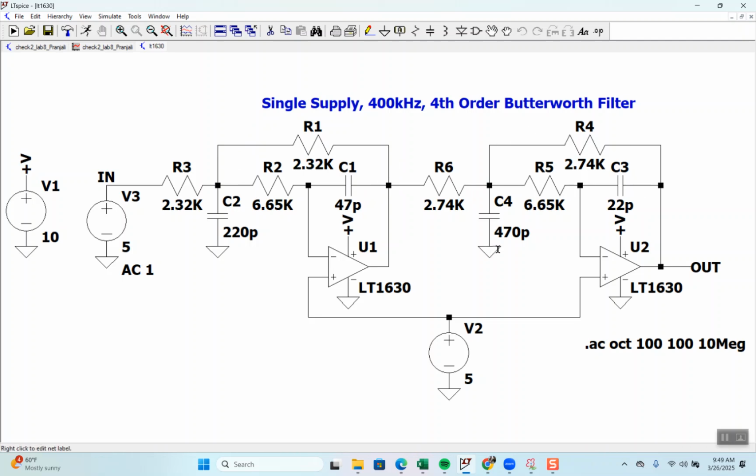And you might wonder why 5 parts versus 4. And now that it's inverting, I need to have -5 volts. But they've done a trick to where you can still make it a positive supply, right?